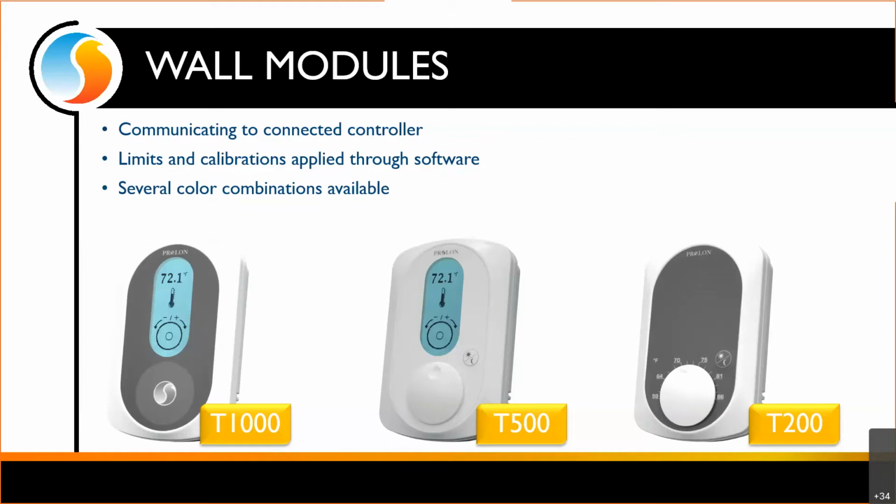And then with the T1000, this one has a digital display and a touchpad. So when we're changing the set point, it's very similar to how you operate an iPod. It's just a circular motion with your finger. You can push the set point up or down. Now, the T1000 has a certain menu structure. However, we have not included any menus right now for rooftop unit controllers. The menu structure is only designed for VAV controllers, so we're going to get into that next week.